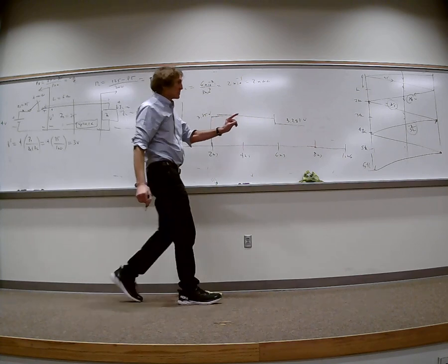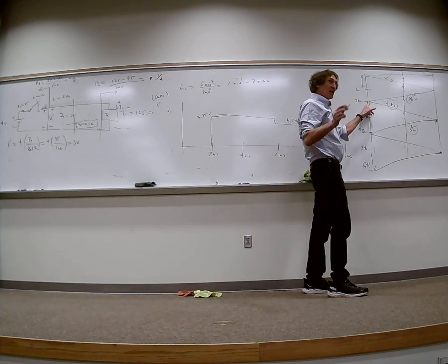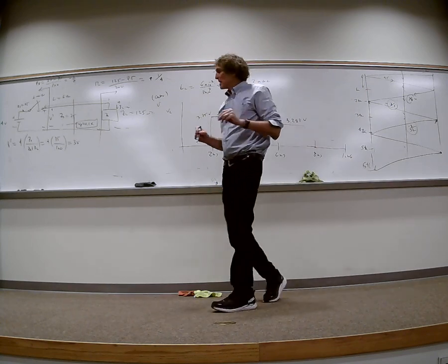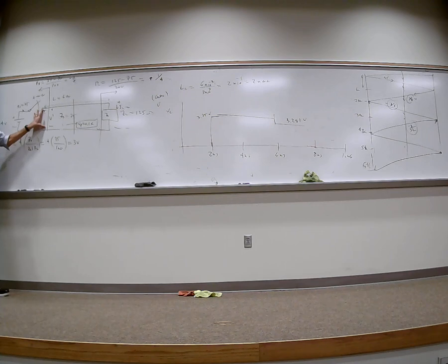And remember, that's a superposition of these things at the time, right? Then you have to take that voltage. Now, hear me. Take that voltage, don't divide by Z0, don't do anything like that. Here's what you do. You take the VS, the 4 volts, and you subtract that voltage from it, and then you divide by RS, because that's the voltage across that resistance. You all hear me? That will be the current that's going to be moving onto the transmission line.